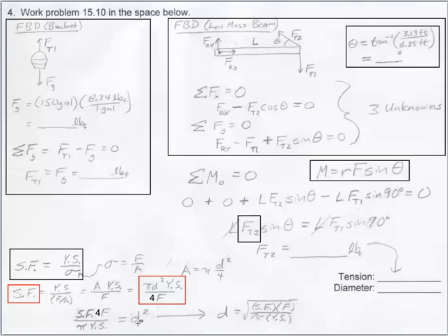So what I've done here is I pulled from right here, going down, get an arrow on this. All right, so I'm taking the D squared right there from that equation. So from right here down like that, okay? And then that means I'm going to take the 4F and move it from the denominator here to the numerator over here. So I still have the safety factor right there, safety factor times 4F. And then I'm going to take the things out that's not D squared and divide both sides by that. So I have pi yield strength, pi yield strength.